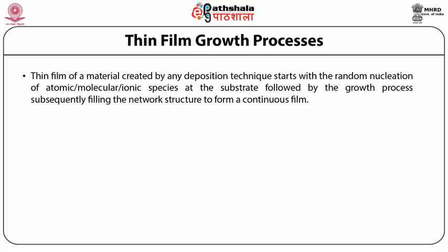The nucleation and growth stage depends on the deposition conditions such as substrate chemistry, growth temperature, processing ambient and growth rate, and can be modified significantly by electron or ion bombardment.